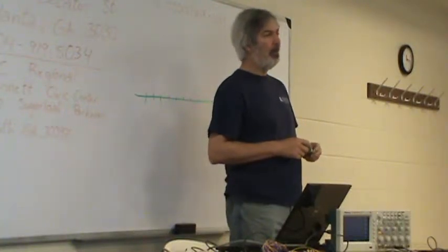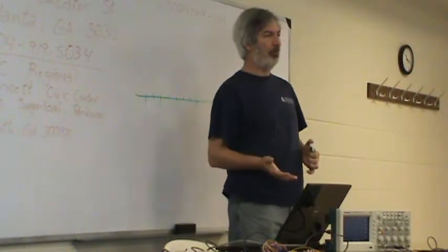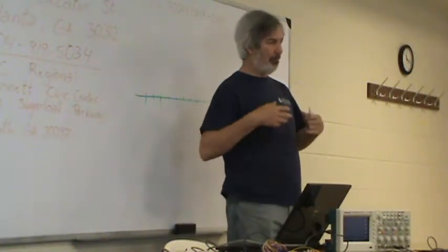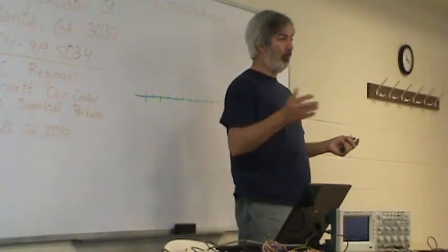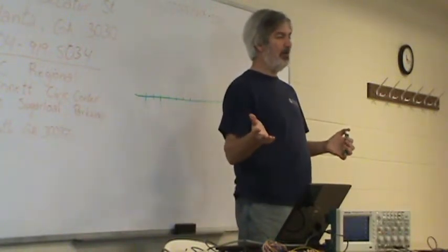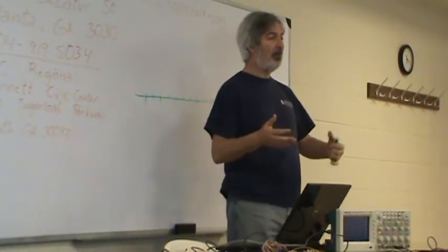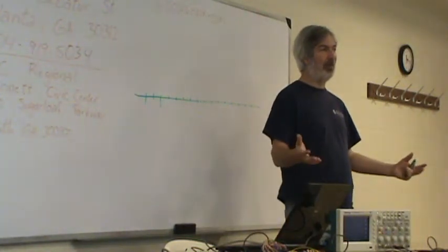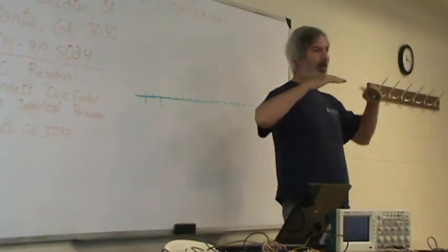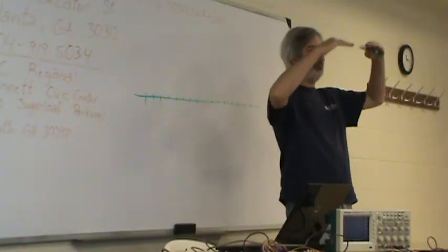But if you've got a circuit that has a variable current draw, where maybe you run a servo, and that servo only runs periodically, and it works most of the time, but maybe you have some other circuit that you also run sometimes at the same time, what you'll end up with is two devices that use different amounts of current that occasionally, between the two of them, exceed your circuit's rating.